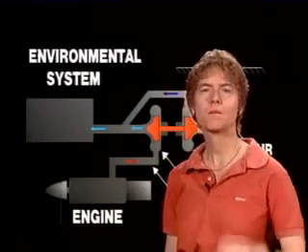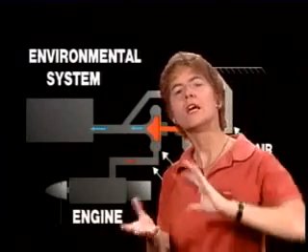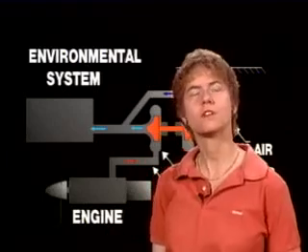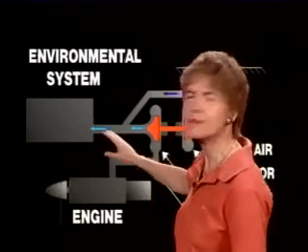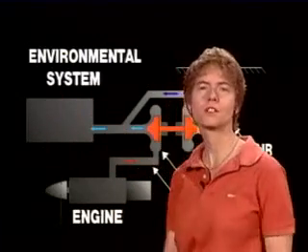Now, sometimes these independent cabin air compressors can become disengaged or quit functioning for one reason or another. And if that happens, you do not want to lose the pressurization air. That is prevented from happening by a check valve in the delivery air duct. So when they ask you, if the cabin air compressor becomes disengaged, what prevents a loss of pressurization, it's not valves in the back of the airplane they're talking about. It is a check valve in the delivery air duct that keeps the air from coming back out through the compressor if that cabin air compressor becomes disengaged.